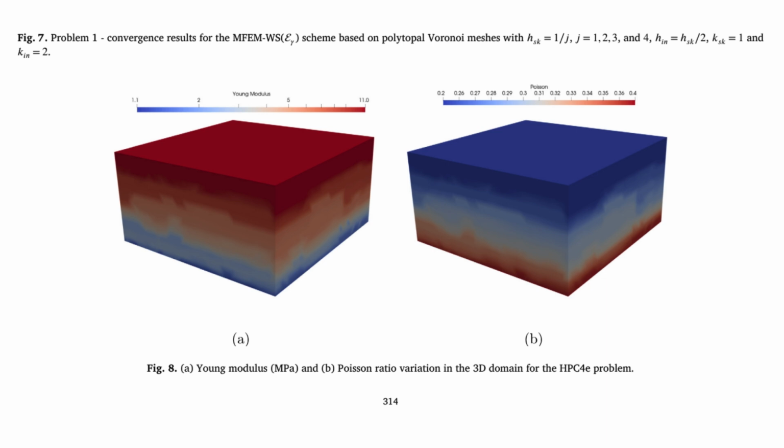That feels like getting extra performance for free almost. It's not quite free, you pay with local computations, but it's cheap. And it doesn't stop there. The displacement accuracy can also get a boost. It can reach an enhanced rate like order l plus 2, which is one order higher than the typical l+1 you might get otherwise. So by spending cheap, parallel computing effort on the local details, you actually improve the accuracy of the overall global solution significantly. That's the idea. The decoupling lets local refinement really punch above its weight in terms of global accuracy.